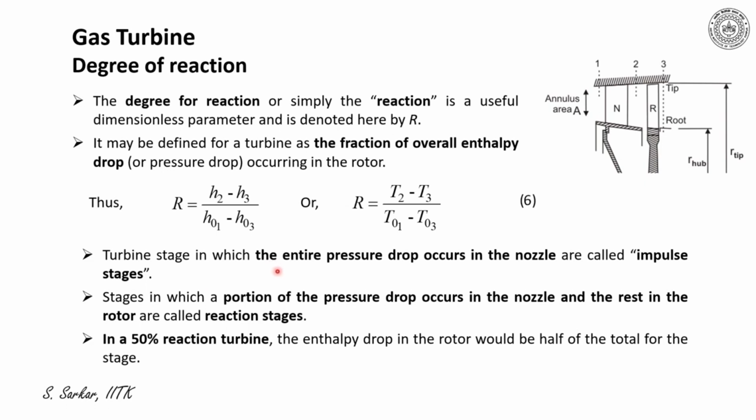Similarly, for a reaction stage, a portion of the pressure drop occurs in the nozzle and the rest occurs in the rotor. Thus, the stages in which a portion of pressure drop occurs in the nozzle and the rest in the rotor are called reaction stages.